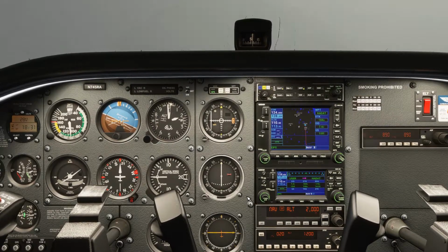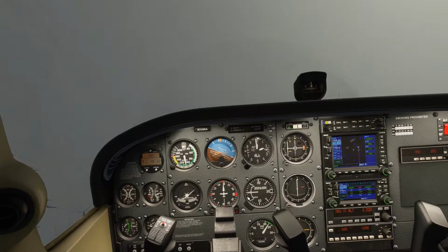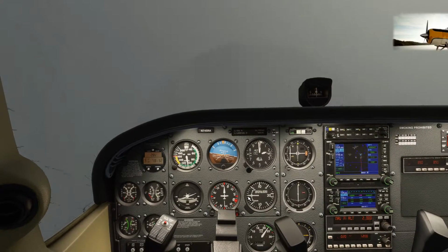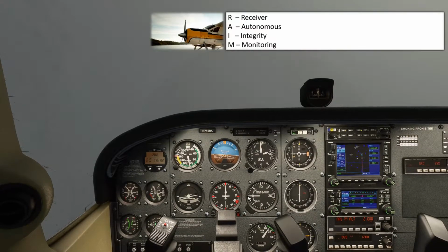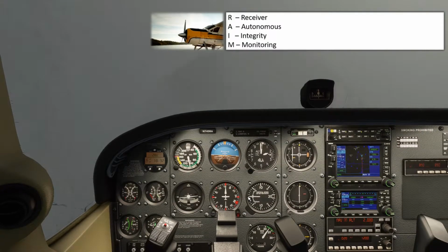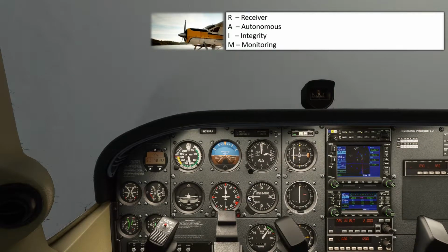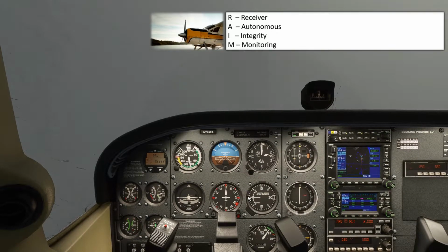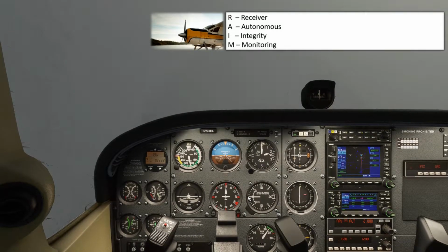That's how you set up the GPS for the RNAV approach. Now what we would have to do as well in real life is to make sure we have something called RAIM available, which is an extra feature on the GPS which allows it to verify the position that it's calculated. That needs a certain number of satellites available, so 4 satellites are required in order to get a position information, 5 satellites required for RAIM, which allows it to cross-check with an additional satellite to make sure the